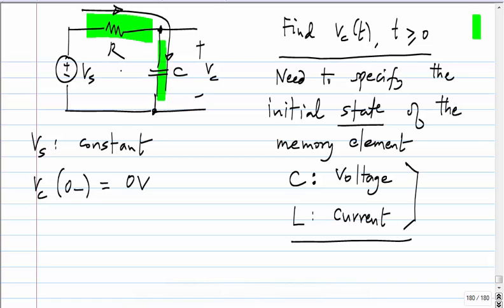I am looking at the capacitor voltage. So what should be the units of rate of charging? dV by dt. So give me some answer that has the dimension. What is the value of dVc by dt? I by C, Vs by RC. Vs by R is the current flowing.